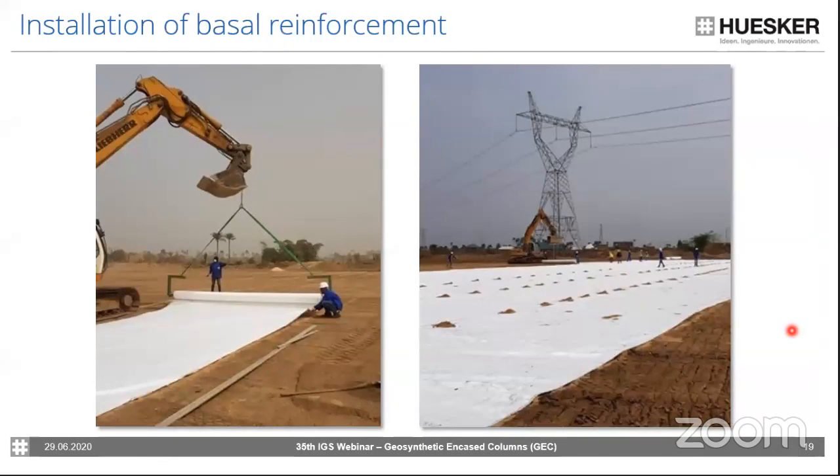When the geotextile encased columns have been installed, a working platform or a transition or load distribution platform is placed, and also the high strength geotextile is unrolled. This can be simplified with an installation frame, and then it can be easily unrolled. To protect the geosynthetic against wind, normally just a sand pile is placed to load it.